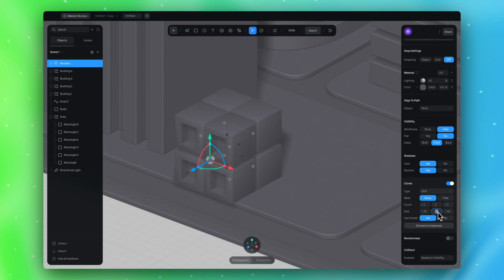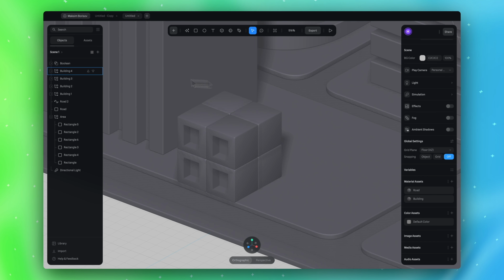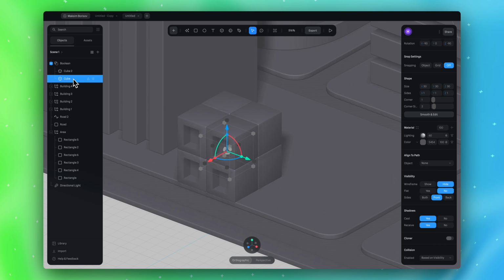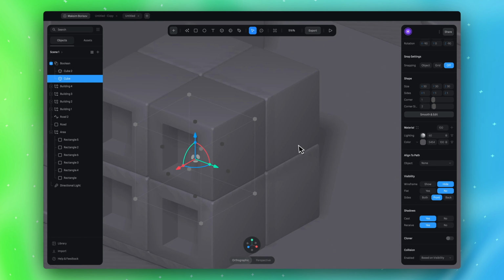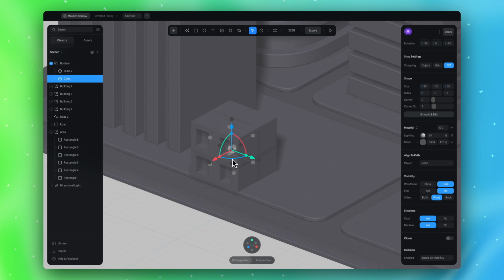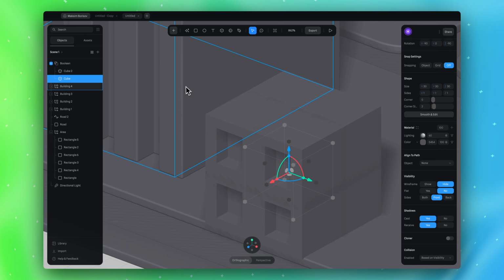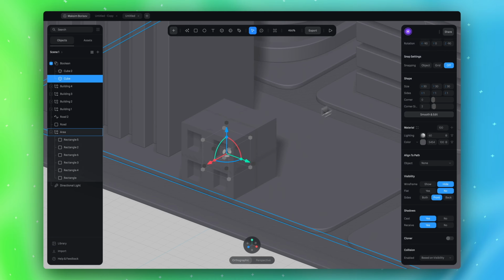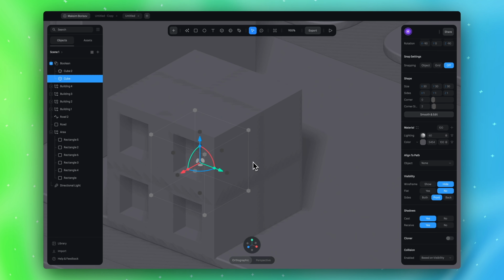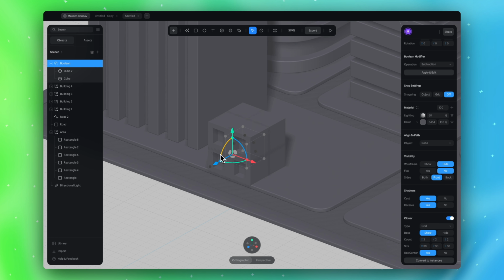Then I will have no space between groups. But I have this kind of weird artifact. Let me select my Boolean cube, maybe because we have corner radius. So let's, yeah, if I turn it off fully, we will not have this nice edge like we have here, or everywhere, but it will be a little bit better because then we will not have the strange artifact.